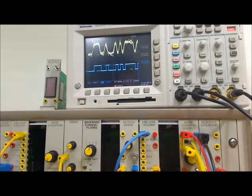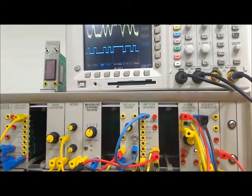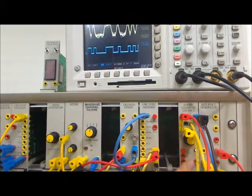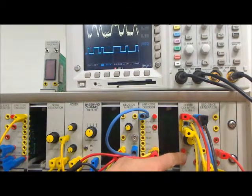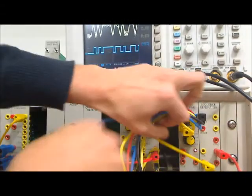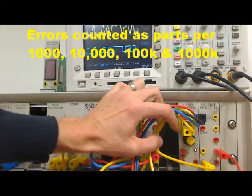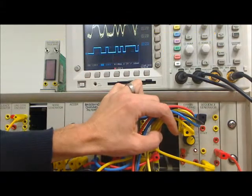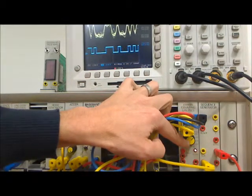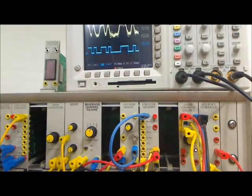So, using the bit error rate instrumentation, we can actually count the number of errors by using the bottom half of the utilities module. It acts as a gate. It allows you to count the number of errors for a certain number of clock cycles, so that you can take measurements of your error rate as a ratio of 10 to the 3, 10 to the 4, 10 to the 5, 10 to the 6 clock periods. So you'll have a well-expressed bit error rate.